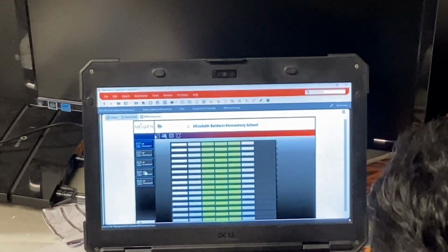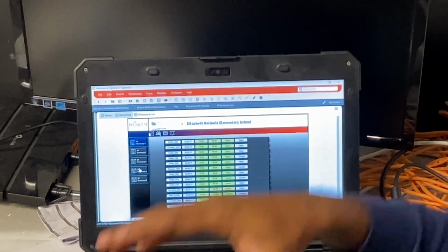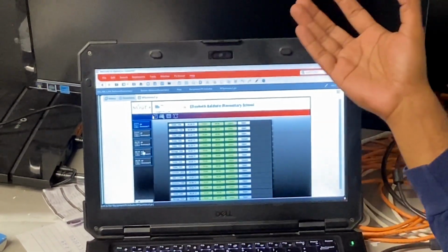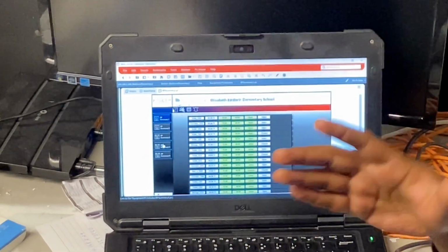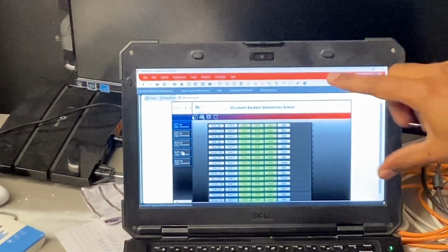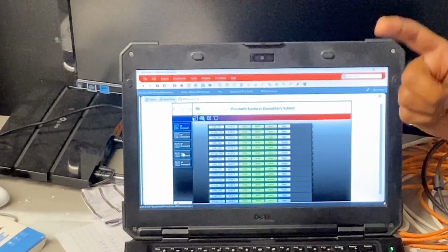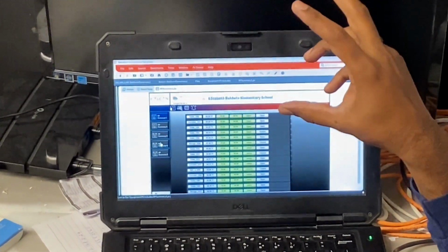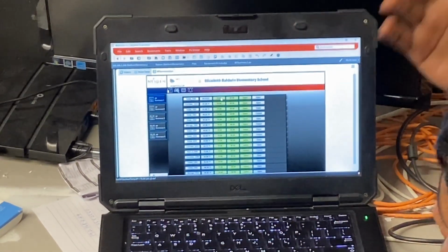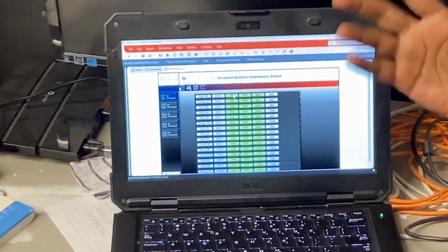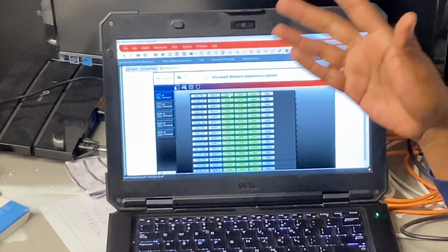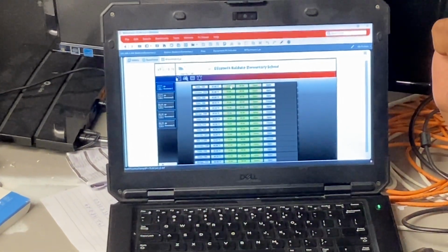And the radiant panel. Apart from VAV, which has its associated radiant heat, we also have standalone radiant heats, just for bathrooms, hallways, and common areas. The standalone radiant heat has a blank plate sensor, and you can set the set point from here, and that drives the valve open. Mostly the standalone radiant panels are open-close type, again based on the space temperature.